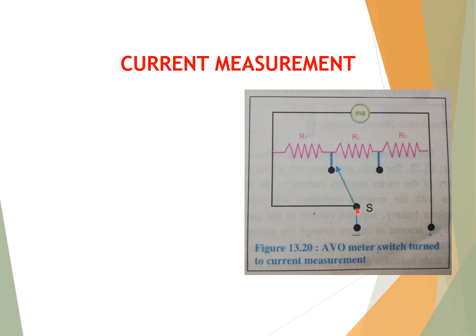So now this circuit is behaving like an ammeter. For the selector switch connected with only one resistance, we can have a small amount of current through the ammeter circuit, and when we increase the resistances, we can have a larger amount of current passing through the ammeter circuit or current measuring circuit. So this value of resistance gives us different ranges of ammeter.